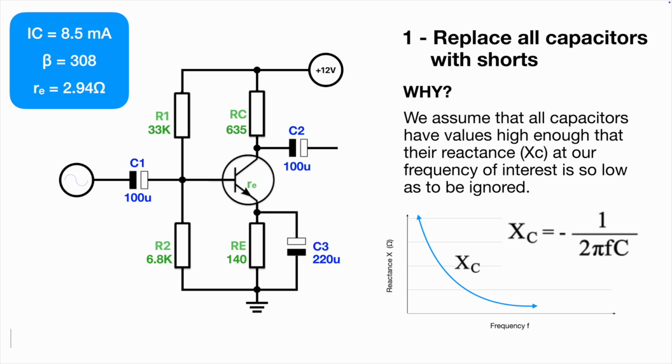So let's say, for instance, if we were building this amplifier for 7 megahertz, let's say it was a little RF preamp, you wouldn't put 100 microfarad capacitors in there. You wouldn't need anything like as high as that. I would just stick in 100 nanofarads as coupling capacitors here and probably here as well. And 7 megahertz with 100 nanofarads would give us a reactance of 0.23 ohms. So hardly anything at all. So that's fine.